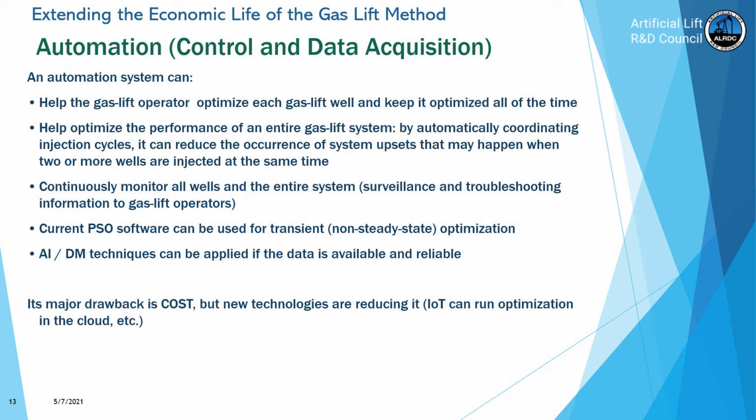And at that moment, we close the intermittent 100%, so that the pressure in the annulus will remain the same until we reach the optimal cycle time. At that moment, the intermittent will open 100%, but it will do so for only a short period of time, because the pressure in the annulus is almost equal to the opening pressure of the valve.